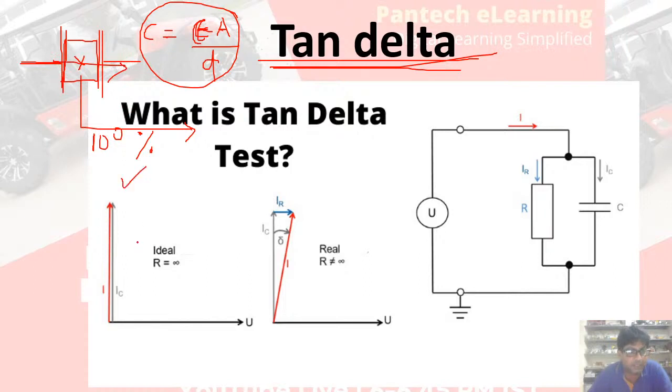The figure is like this: the total current is nothing but the capacitive current. But if there is some degeneration, some breakdown, or some tracking initiated through the insulator, then a resistive component will also come.